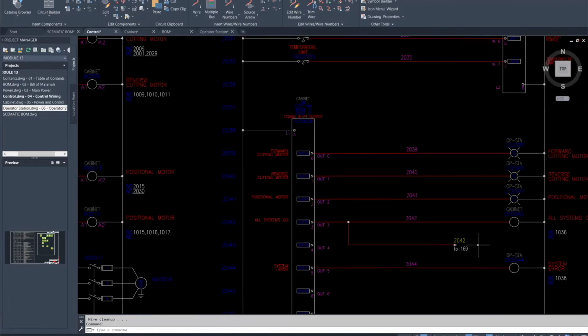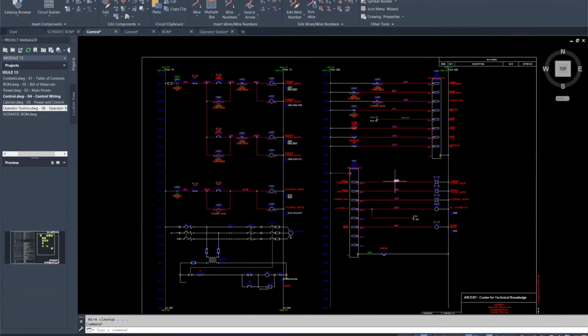I can make a library component out of that. And then someone out in LA is working on a different project, but they go, hey, remember when you put that PLC in with the 3 lights and the push buttons? Yeah, I go, that's saved under library circuit 225, and I can put a description in there. So that's a real time saver. And that's working with schematics and building schematics.